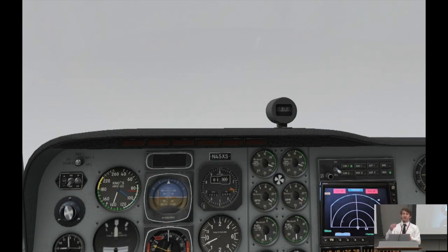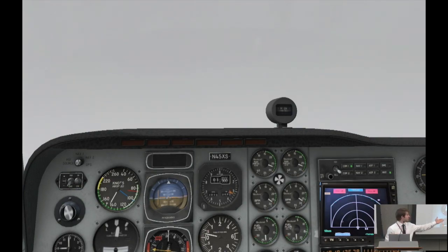Because we're constantly bombarding the multifunction display with these terrain warning messages, we have this denial of service attack where you're no longer able to use your navigational map. Every time you click over to the navigational map, it clicks you back to the terrain warning map, which, as you can see here, really doesn't contain any useful navigational information for where you are in relationship to the runway.